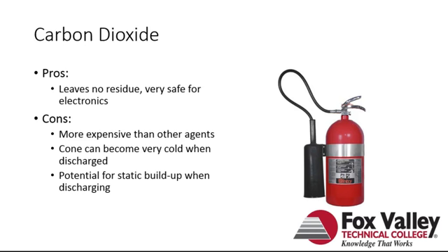Some pros. The biggest thing is it does not leave a residue at all, which makes it safe for electronics. Basically, you're just putting another gas in the area. You're not doing anything that's going to damage the actual electronics. Water obviously has the issue that you can start corroding. A lot of your dry chemical, same thing, is very corrosive to electronics, so you have to be very careful with that as well. So it leaves no residue, so it's safe for electronics.